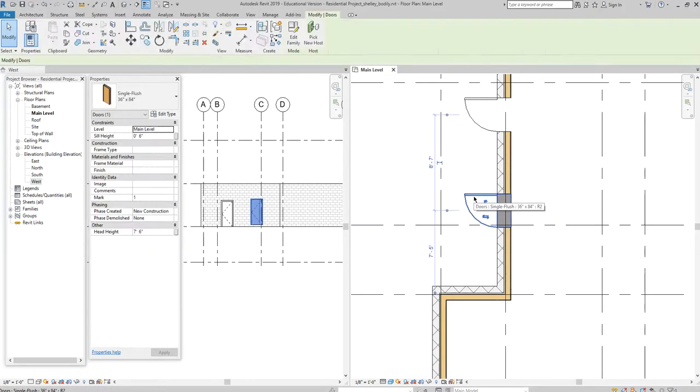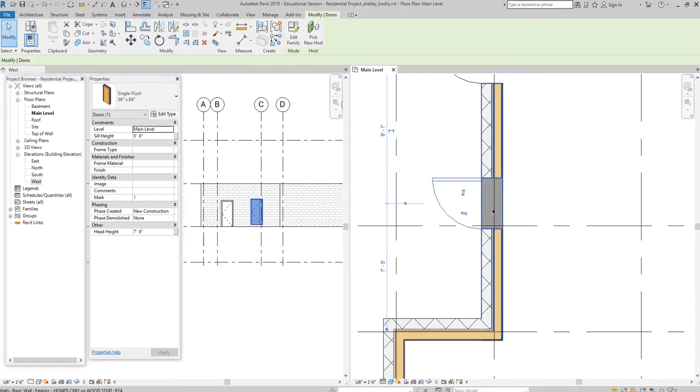I can click on that door again, and I could change it to, well, I don't have any wall up here, so it's not going to work, but you get the idea. You could change the level that it rests at, okay? If I click on this door, a couple things you want to notice. We have these little grips that will allow you, this is magic too if you've been using AutoCAD, right? Click, oh, flips the swing, right? Oh, look at that. Interior to exterior, side to side, left hand, right hand, right? I can change how these things function, okay?